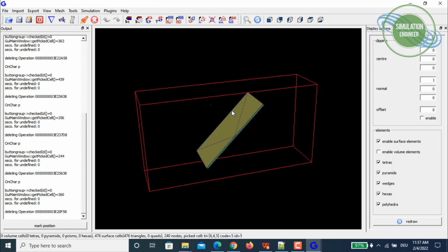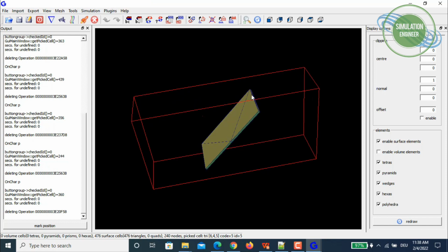So if you want, you can define one boundary code and select all the patches one by one, and always give the same boundary code. So then, for example, if the next one will be number 7, number 7 will contain all the patches of the damper part. But I will be deliberately using different patch ID numbers for each damper surface. That will help us in performing mesh refinements. For example, the damper edge refinements, as already shown to you in the slide, and later on we will be doing surface mesh refinement in the vicinity of this damper.